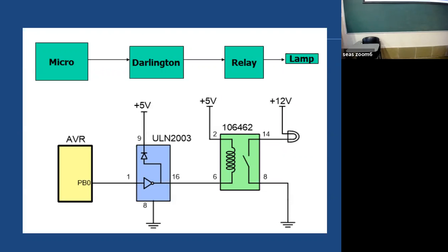All right. So you should understand this diagram well. This is a real life application of AVR. And if you want to note down, you can do that. And we have the port pin. And this is just an amplifier, a current amplifier. And the right voltage will turn on this circuit. The magnetic field will turn the switch on or off. And we have another circuit on the second side. You should understand this.